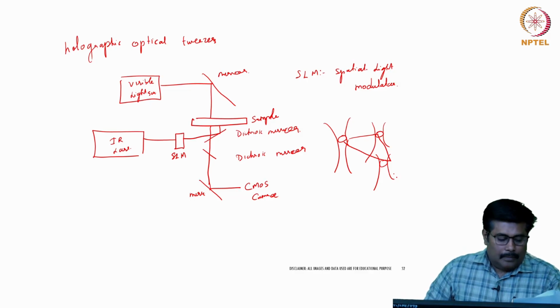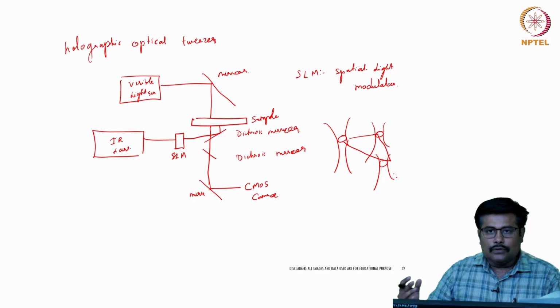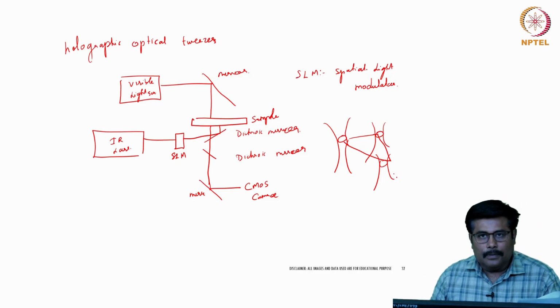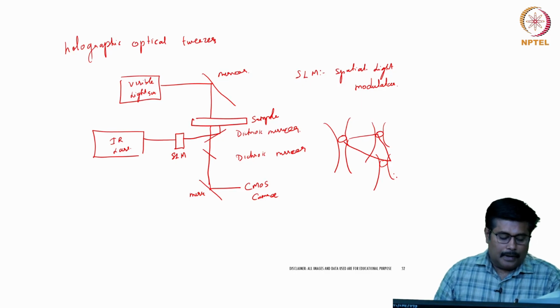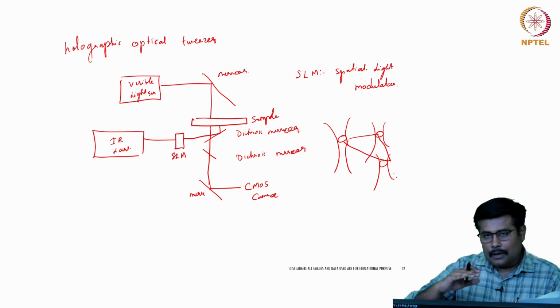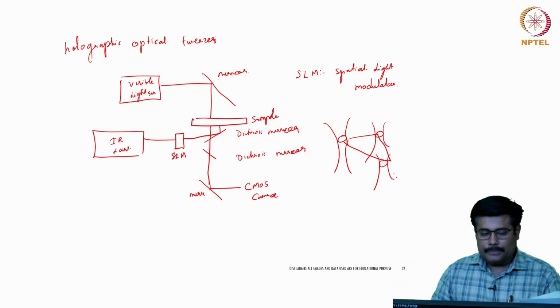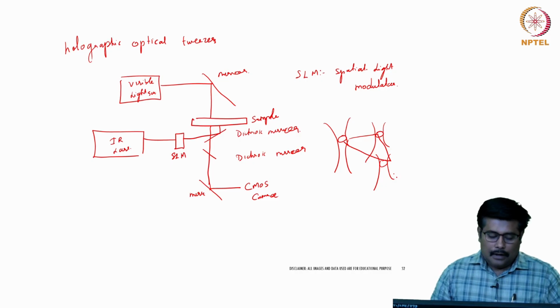Trapping multiple parts of a structure via different focal points has been used to control the planar rotation of a micro robot. However, out of plane orientation control is difficult to implement, since the focal points of the optical laser traps are constrained in the same focal plane, so a special design of a micro robot is required to achieve out of plane manipulation. So, let us discuss the overall system configuration of these optical tweezers.